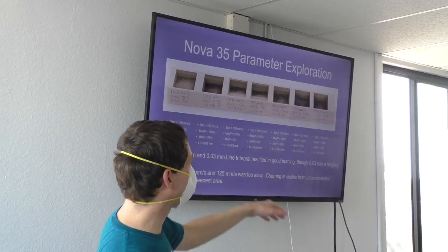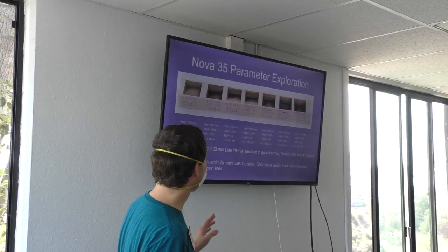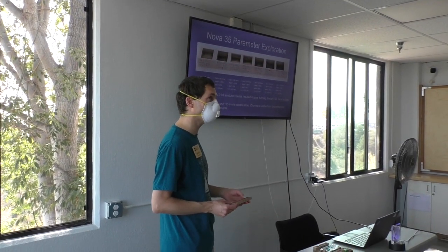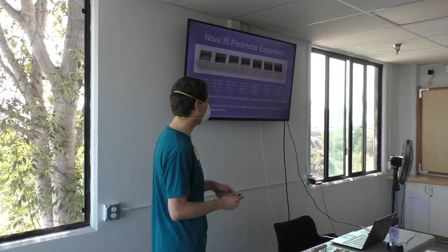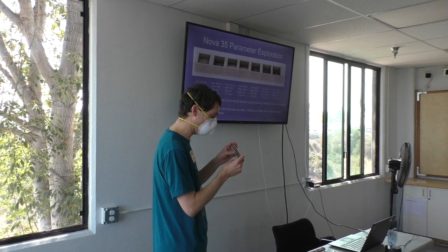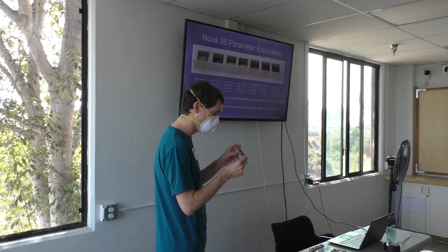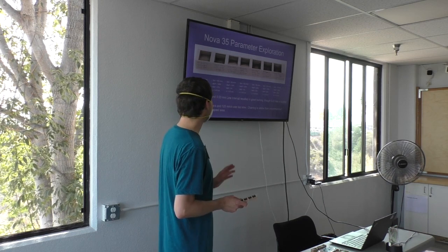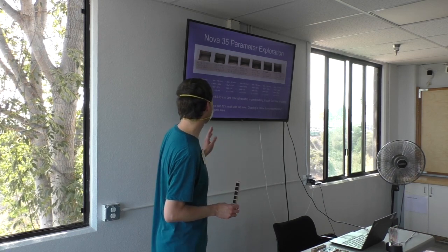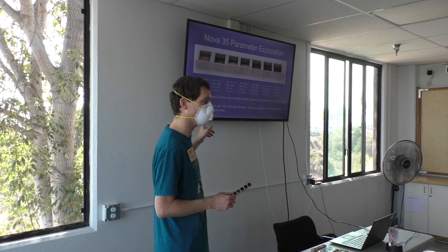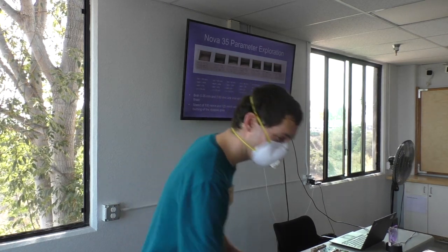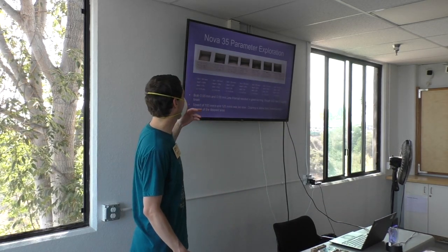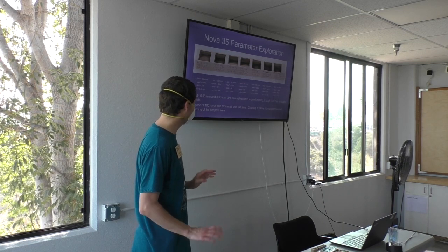I tried various different settings, and the most exciting are the last two. Those are 100 millimeters a second and 125. If you look closely, you can see on the back edge that the burning was uncommanded. That's going to ruin your design, so that's too slow, besides being dangerous. And then the 0.05 versus 0.03 for the line interval, both seem to give good results. The 0.03 is going to get you deeper, but it has a rougher texture in the lower parts. So that's what those are at.